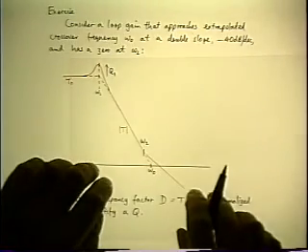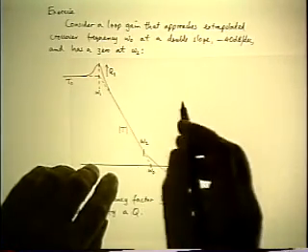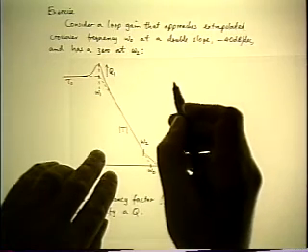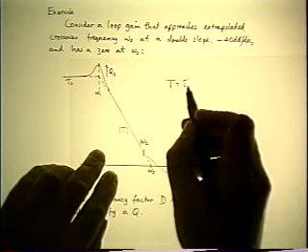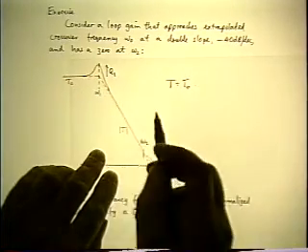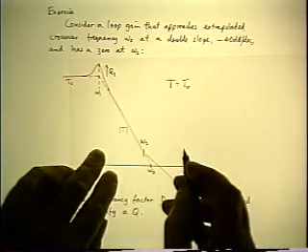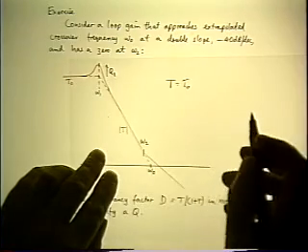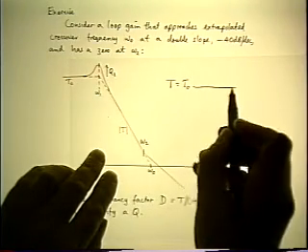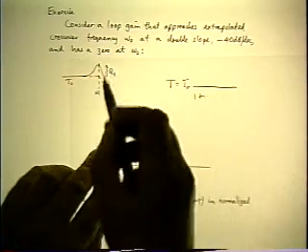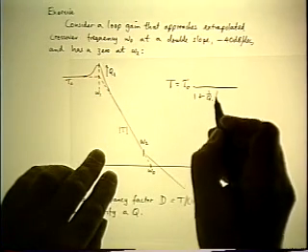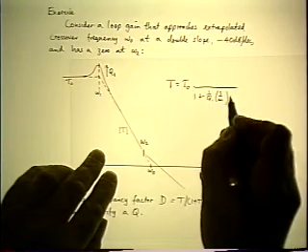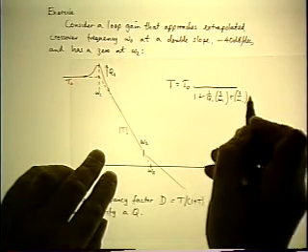Well, before you get too far along with that, let me start it off using the flat gain as reference, T equals T0. You look up in frequency and you see a concave downwards corner, which in this case is a double corner. So you represent that by the standard quadratic, and the parameters are already given: 1 over Q1, s over omega 1, plus s over omega 1 squared.